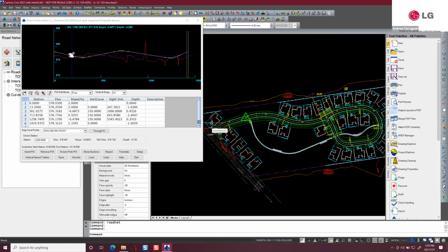When we're putting in even large interceptor sewers, when we run them down by the rivers, it's called the Three Rivers area here, the Three Rivers Stadium and all that. We've had miles of this where we have to put concrete pads under the sewer line. They call them mud mats here, because the ground is just mud all the way down. Yeah, the ground here is clay, but it's very, very, very wet.